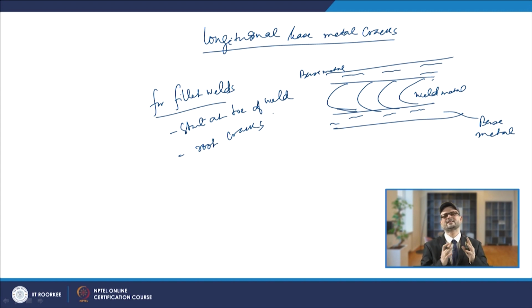Whenever you have steels with higher hardenability, as we have studied earlier, cracks are more likely to be seen, because the steel cannot accommodate the stresses. So, you should have the proper combination of the base metal and the filler metal, so that you avoid that hardenability problem.